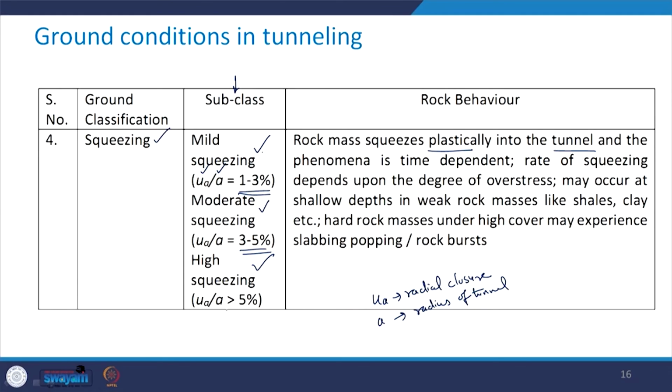Why we need to be careful about it: if the rock mass is squeezing and you want to construct a tunnel of, say, 10 meter diameter, then you have excavated and the rock mass has this characteristic of squeezing. What will happen if you leave it unsupported for some time? It will start squeezing and the tunnel diameter will reduce and it will not be the 10 meters which is required. So, we need to be extra careful if we encounter this type of ground condition.